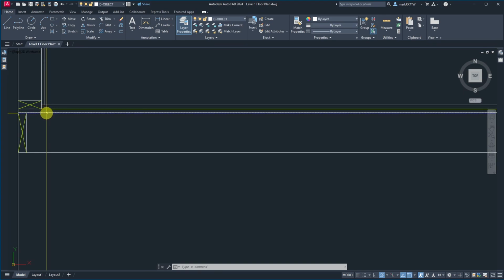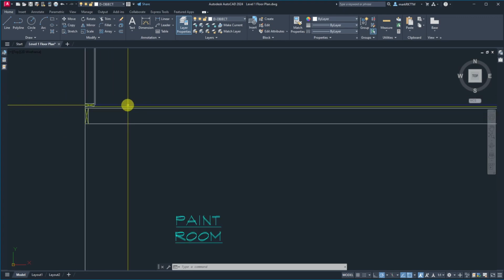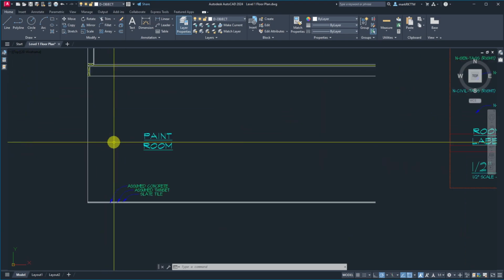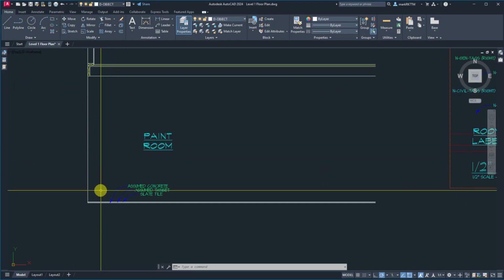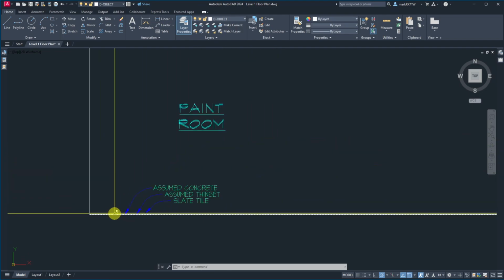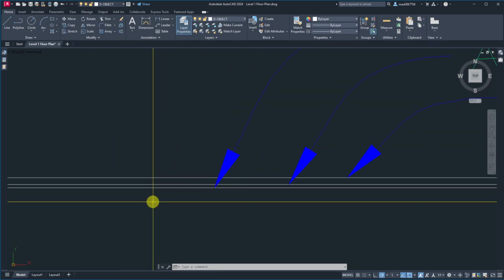There's a 3/4 inch angled planking, at a 45-degree angle, typical of old construction. And then I'm making the assumption that I've got a 3/4 inch hardwood on top. It is a true hardwood. Whether it's 3/4 or half, I'm not sure, but the plate dimension works out pretty sweet with that assumed. And so here I do have some assumptions because I did this from my paint room downstairs, just to keep things from freezing in that room.